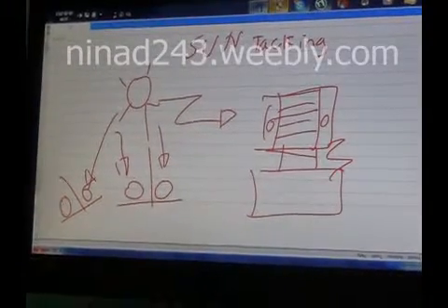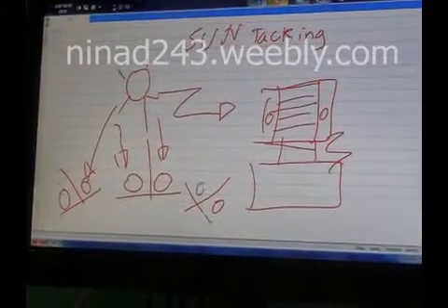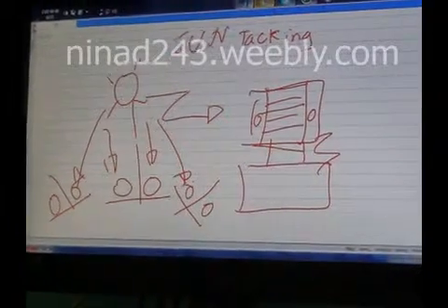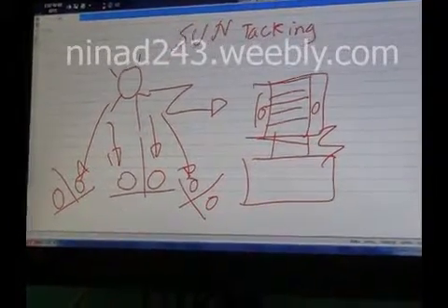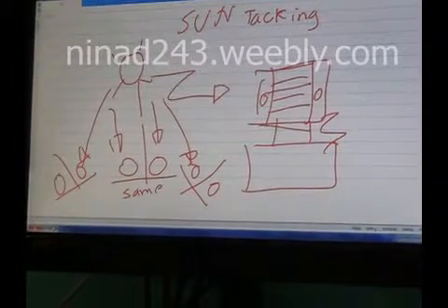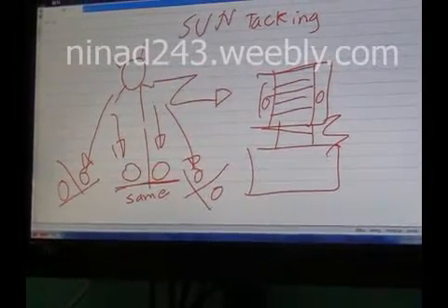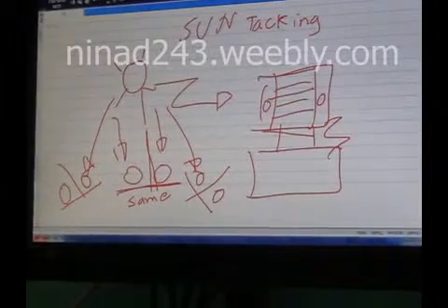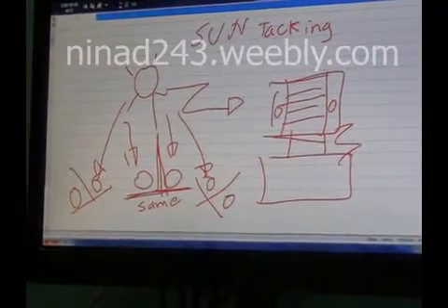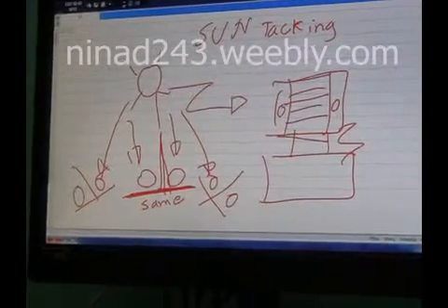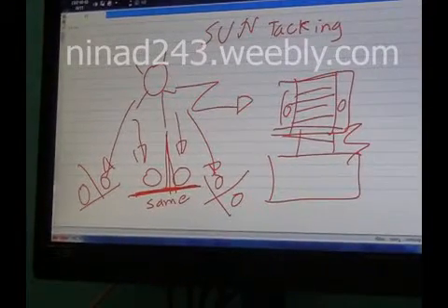If you tilt it on the other side, then this LDR will receive more light. So the only possibility where they are the same is the center location, and this is how it is adjusted to be perpendicular to the sun. Now when this plate is perpendicular to the sun, this plate is facing the sun, and this plate is your panel.